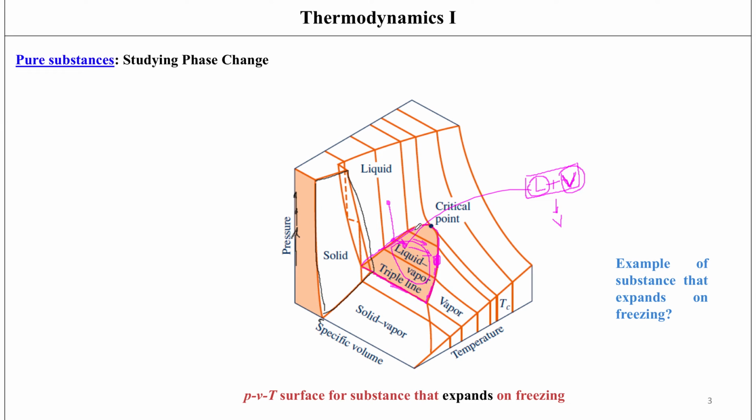This saturated liquid, it means saturation. So the liquid has been saturated. It exists completely as a liquid here, and it's about to turn into a vapor. And now the temperature is going to remain constant. The specific volume is going to start increasing, and I'm going to move across this line until I reach the vapor part of it. And now I can increase the temperature when the water has been completely converted into a vapor.